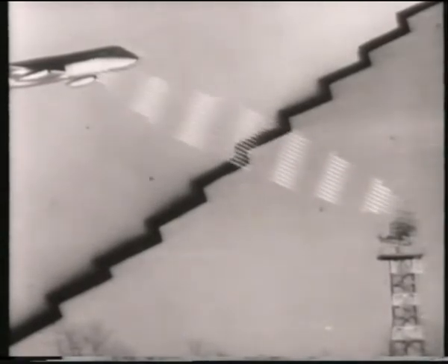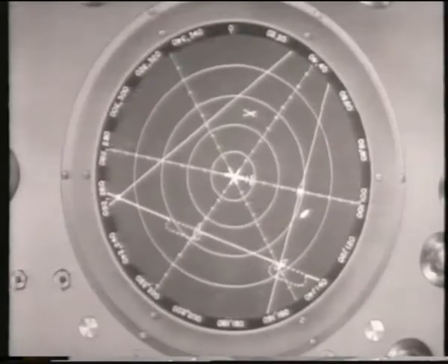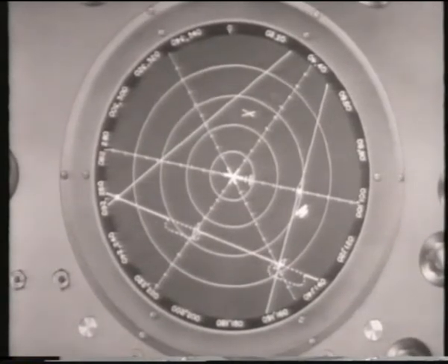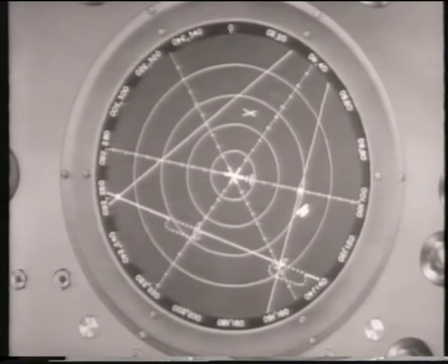The transponder signal received back at the secondary radar antenna is much stronger than the reflected radio energy signal being received by the primary radar antenna. This stronger signal is also seen on the SRE scope, aligned right with the primary echo. It is a much stronger, brighter spot of light.